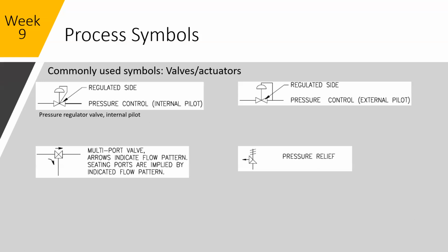So here we have a pressure regulating valve with an internal pilot. The valve controls the pressure to a desired value, and feedback is received from that internal pilot. It's set somewhere in here; there'll be a regulator that is set to 30 PSI. The 30 PSI is measured, and this is calibrated so that this valve is holding 30 PSI in one of the areas inside this valve. It's hard to tell which one specifically, but this is a diaphragm valve.